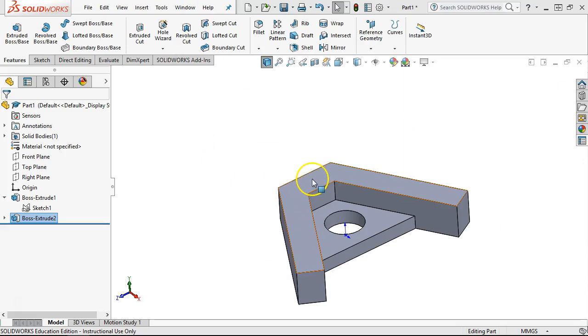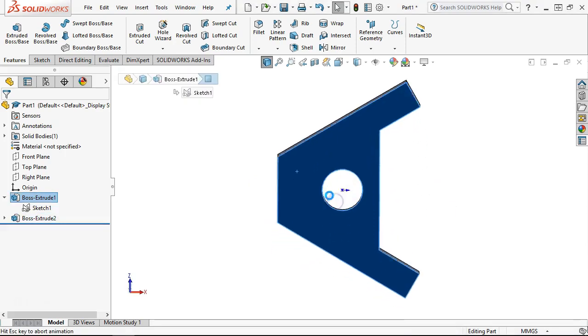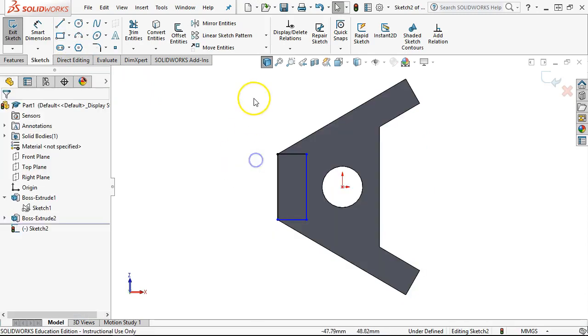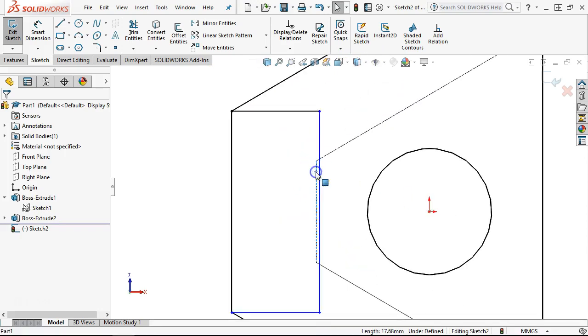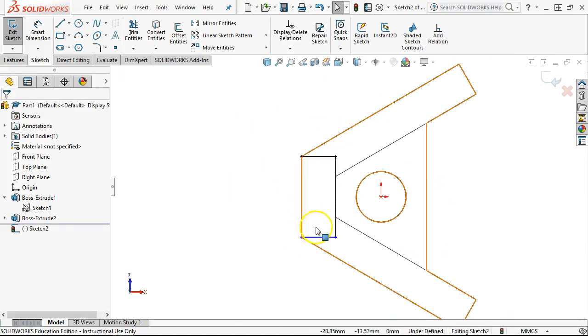And then I have to make a decision on what to do with this piece, because the 20, we said this would be 12, but the hole center is actually at 13. All right, so coming off of that face, or do I just go ahead and say I can sketch on the bottom, and I can use that geometry. Go back into my wireframes, pick up something collinear or coincident.